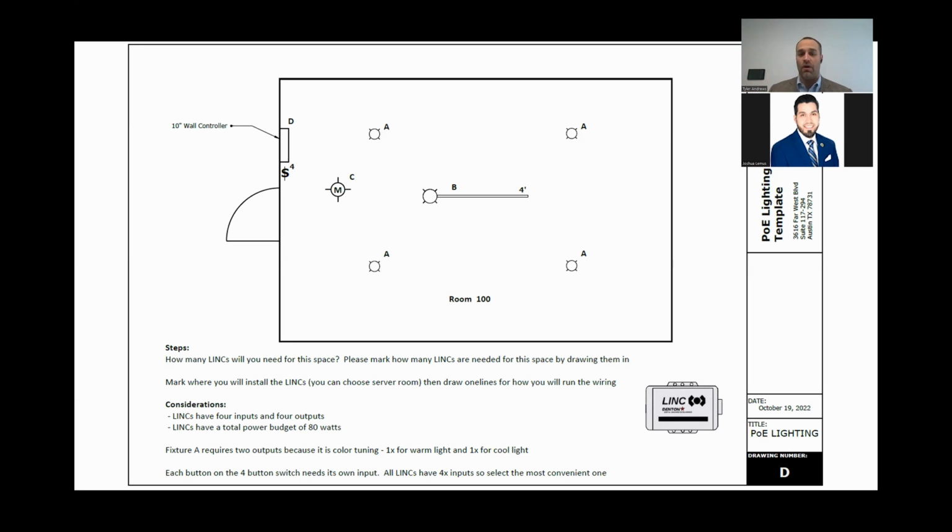So one of the ways I'll draw it here on my screen so you guys could see how I might do it. You could drop a link in on the left side and the right side. You could drop a link in on the top and bottom, and then you would run 1 pair of 18.4 to this fixture, 1 pair to that fixture, and so on. Sorry, I said 18.2, these would be 18.4. So I would run an 18.4 to each one of those because they have 2 constant current channels.